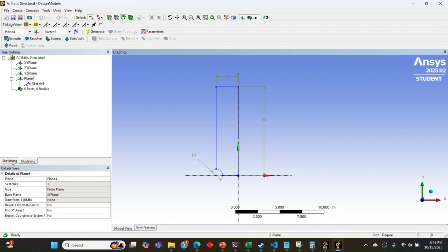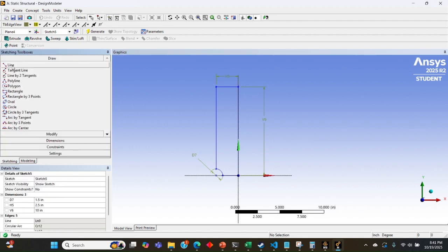And if you want to draw, you go over here to the sketching tab, and there are some options for geometry that you can draw. In this instance, I drew a line, a few lines, and a circle. To draw a line, you can click two points, and if you see that V show up, it means that it will snap the line to a vertical orientation.